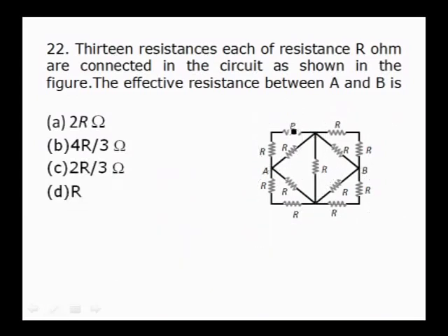Yes. See, these two are in series. Its effective resistance is 2R. This 2R is in parallel with the R. Calculate the value of the resistance. That is Rp is equal to R into 2R divided by R plus 2R.